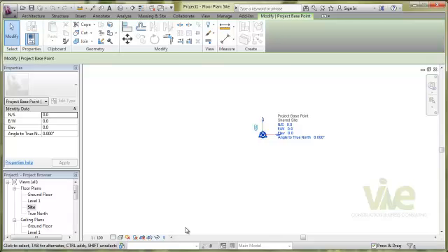It is very important, especially when we are modeling multiple models. If we have, for example, an architectural model, a structural model, and a MEP model, it is important that we keep the same project base point and a similar reference in all models. Likewise, we may have a project made up of an east wing, north wing, central building, and so on.